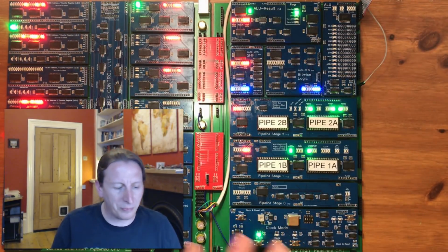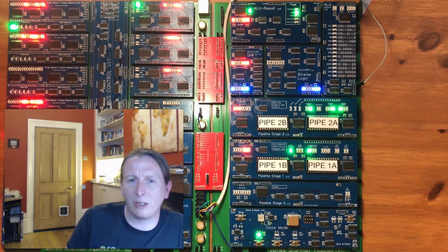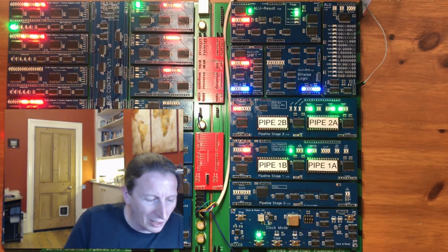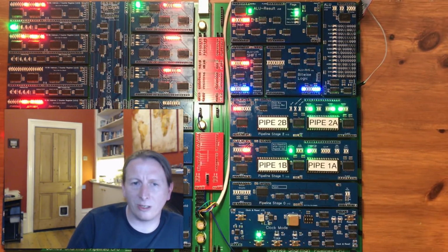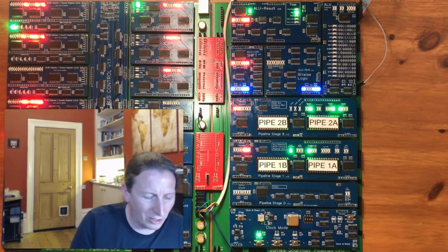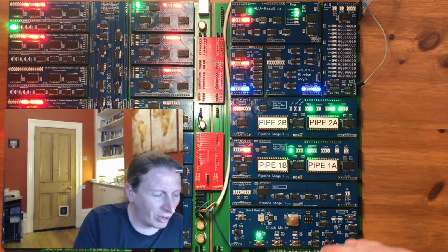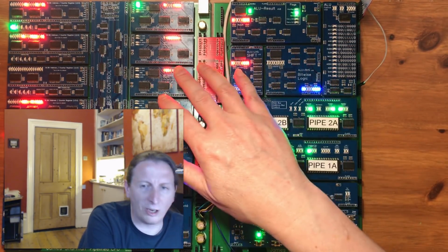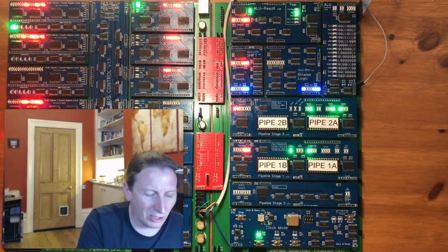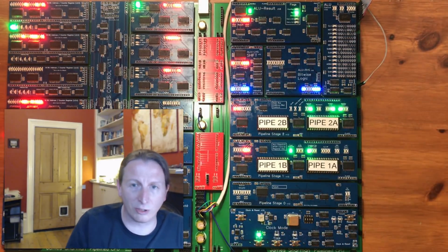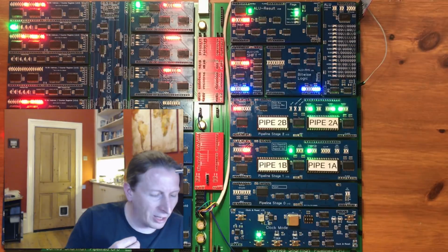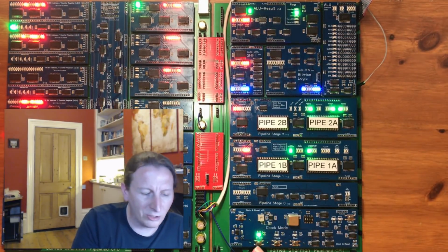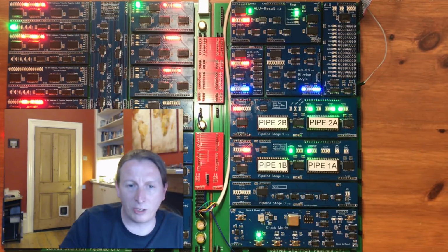And you do specifically mention in your comment Ben Eater's SAP-1 processor. Now, he's got a very small number of registers, so he has control lines from the control unit directly driving the operation of those registers. So what I'm calling load and assert operations, he has those as outputs from his control ROMs that he stores his microcode in. And if you tried to do that for a more complicated processor, you would find yourself with a large number of control lines very quickly.